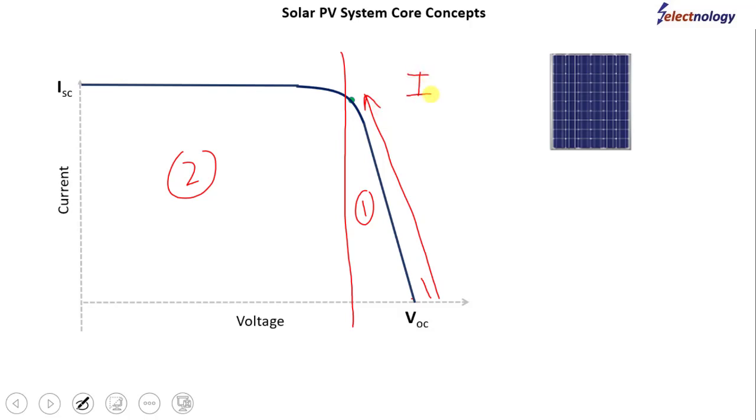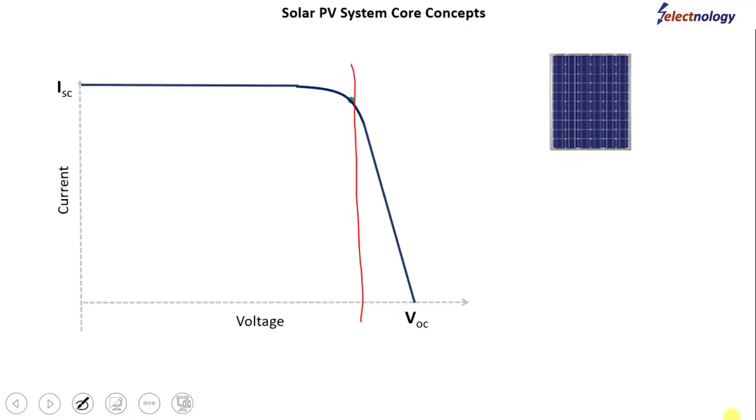So the relationship between current and voltage is reversed. This equation means that if the current increases, the voltage decreases. This is what we have measured, and this is how the relationship between the voltage and current of the PV module works. In other words, if the load increases or the current increases, the voltage across the terminals will decrease.